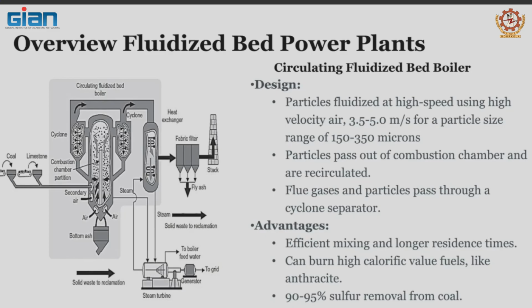If you ever design or take part in designing a power plant, you will see that when you use especially high sulfur coal, and of course nowadays you cannot not use a flue gas desulfurizer, they can be as expensive as the total plant. They are very expensive, especially if you're adding on to an existing plant. So the advantage of this limestone is that it is very cheap.